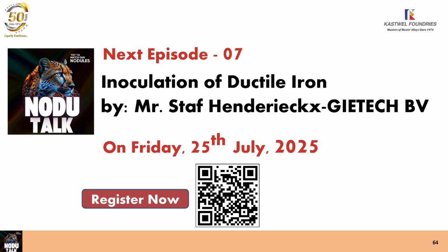And I have to tell you something very important. Maybe some suppliers will not like to hear it. A filter will not filter dross. A filter will not filter liquid slag. So please prevent them and don't try to hold them with a filter, because it will not be possible.